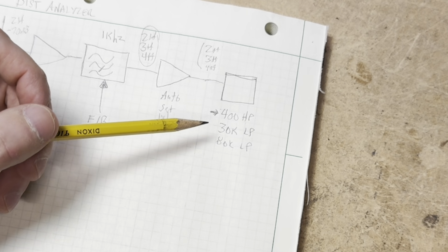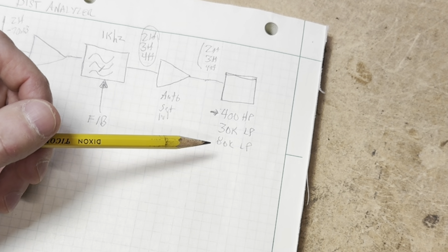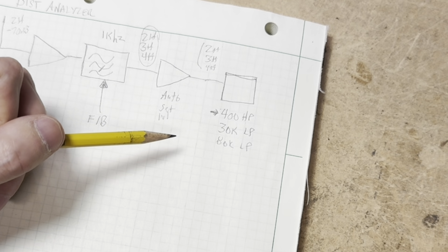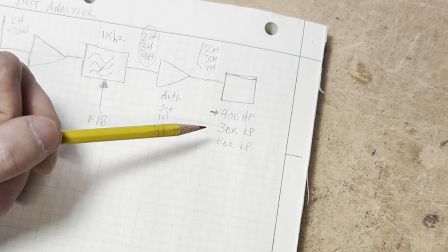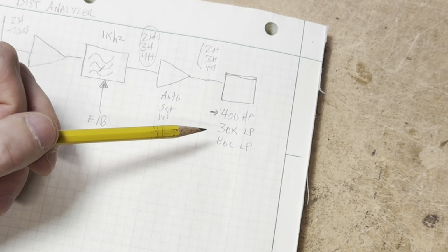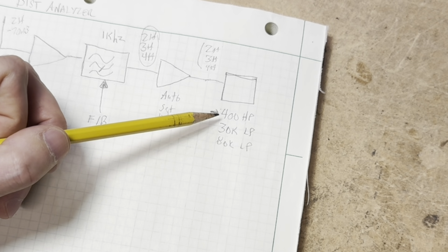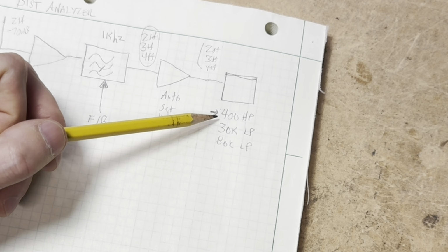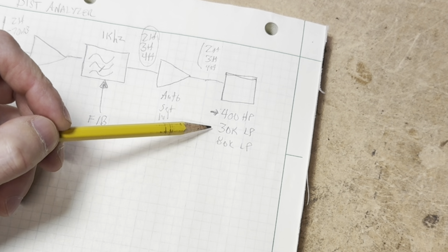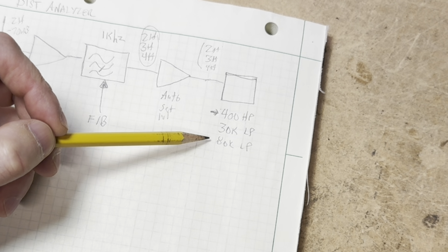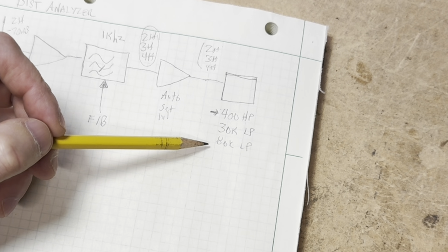Say we're doing production line testing, the noise in a production lab may be different than noise at the end user's home. So we don't want to attribute those noises that may be due to our setup and say blanketly that they are always applicable, because they're not. So we may use a 400 hertz high pass filter to remove the power line noises or setup noise. Again, if we're using 1 kilohertz, we may also choose to apply the 30 or 80 kilohertz low-pass filters. That's going to limit our high-frequency noise that's maybe present in the system, but it's not due to our device under test.